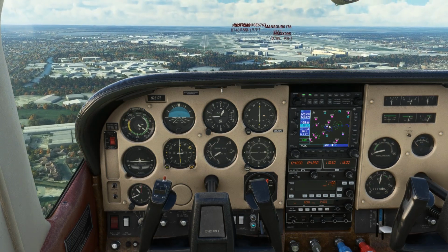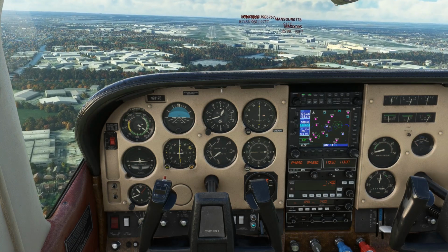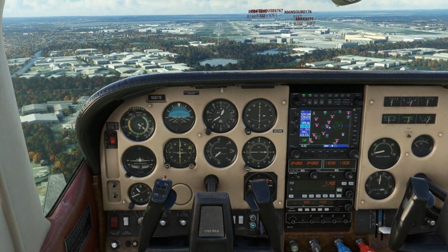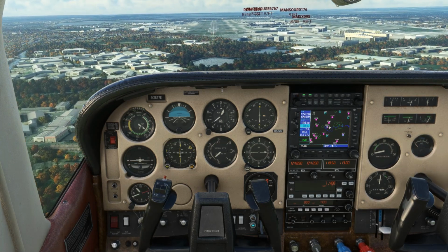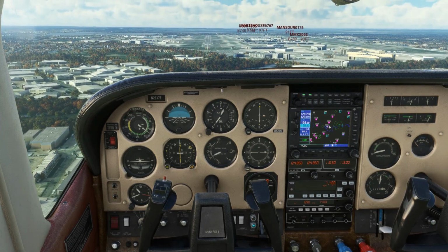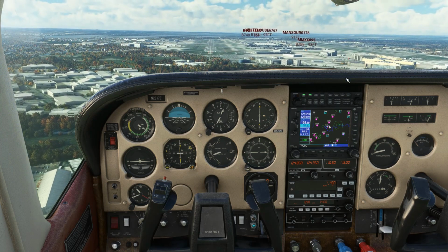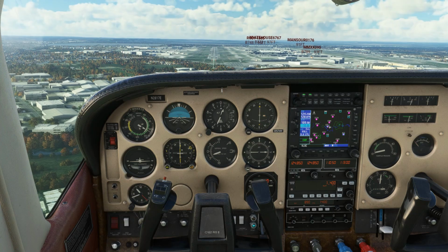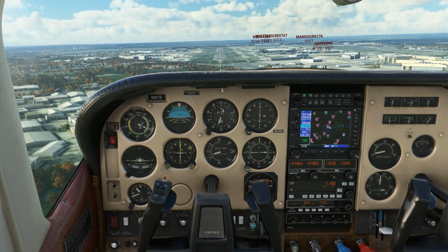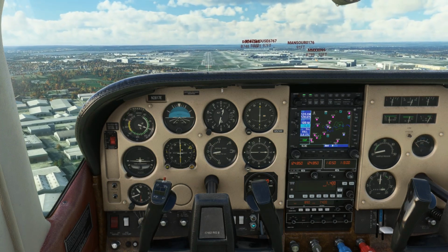When I put in flaps, the nose wants to raise a little bit more than I want, but bringing back that throttle will ease that, so I don't have to put too much pushing or pulling on the yoke, and I can keep a good glide path. Bit low there, as you see from the indicators and the PAPI lights. They're above me now, so I'm just going to raise my nose, get those indicators back to the centre. And the PAPI lights, two whites, two reds as well.